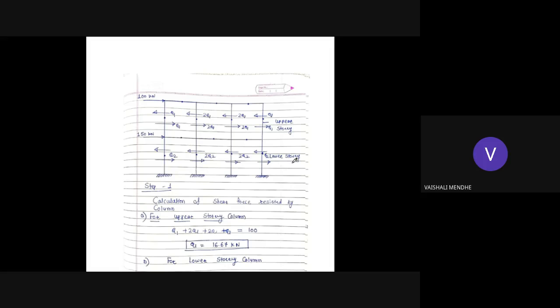So we have assumed it and shown it here for the upper as well as the lower story. First of all, you locate the point of contraflexure. This is our assumption number 1. First locate the point of contraflexure at the center of the beam and center of the column, for each column and each beam member. This is as per assumptions 1 and 2. Then go for the third assumption, where you find the horizontal shear, or simply the shear resisted by the column, or column shear.